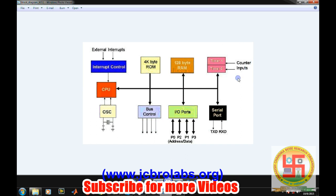Similarly, it has two 16-bit timers, and those timers are particularly used for providing delay and for providing the clock for the serial port. It also has interrupt control, with internal interrupts as well as external interrupts. It has two external interrupts and five or six internal interrupts related to timers, serial port communication and other functions as well. So this is the general block diagram of it.